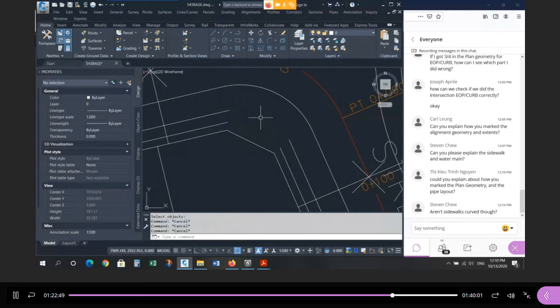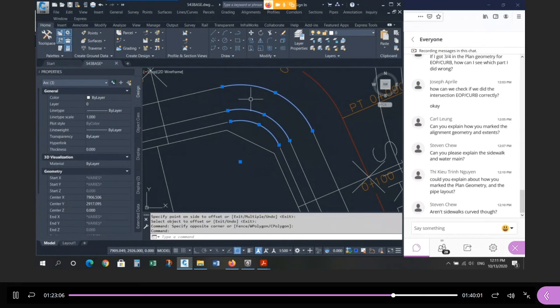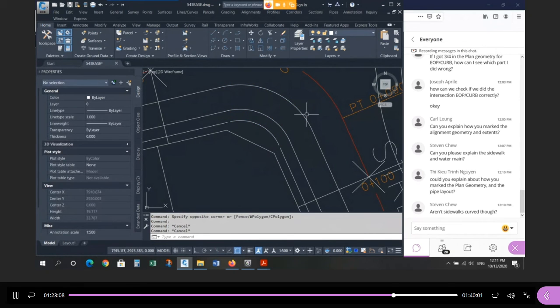There are options here. Here's another option. You could figure out what the offset is here. Offset from here, perpendicular to here, and then just keep that constant all the way around, 1.5. So there's one option for the sidewalk, right? So have these two parallel to the gutter all the way around. Or you could do what I did originally, offset 1 meter from the street line, 1.5 meters from there. So that's another option, this straight piece.